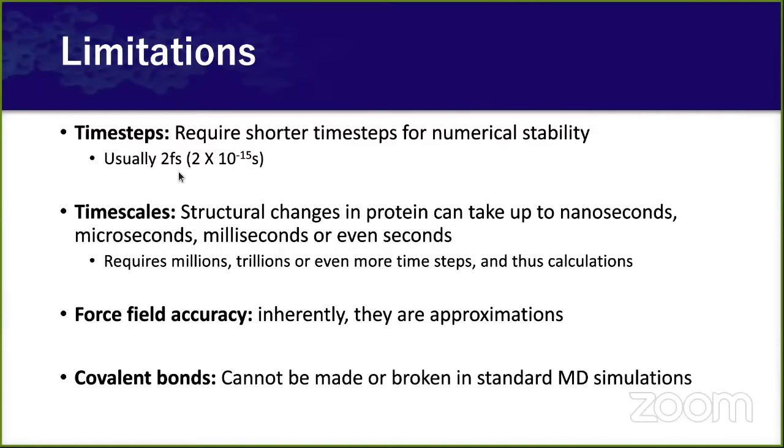Another reason for these time steps to be considered is also the vibrations of the atom. If you look at the smallest time scale at which some atomic movements happen, they usually happen at the femtosecond time scale. Like hydrogen bonds, which are very light and small, they vibrate with a higher frequency. So these movements can happen at the level of femtoseconds, and we have to keep it so that we can also capture those movements during the simulation.